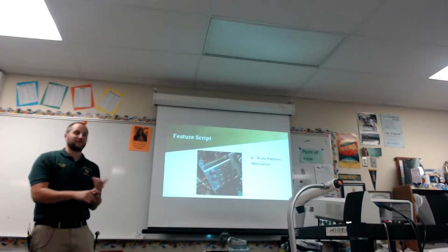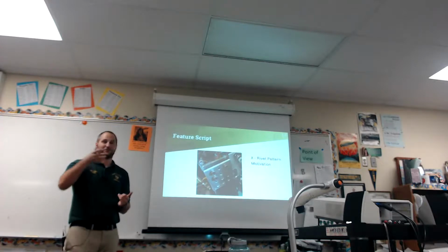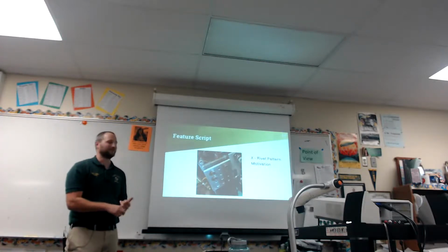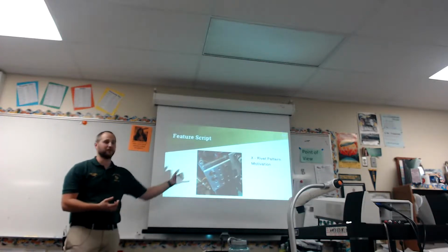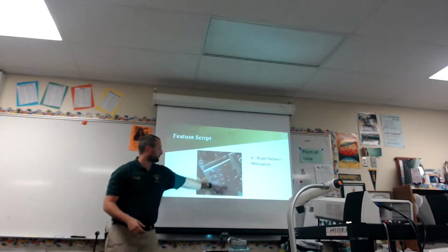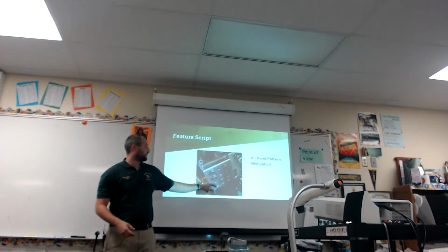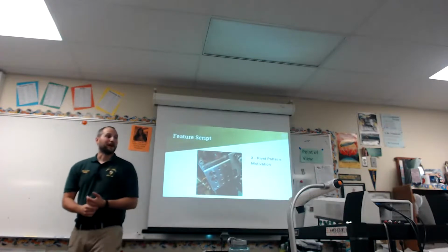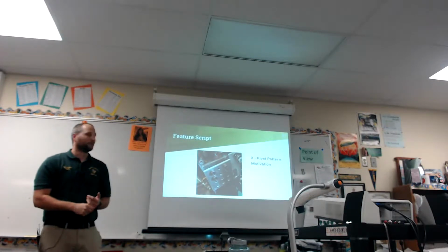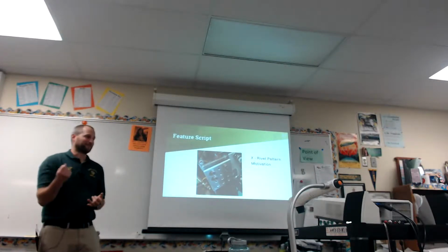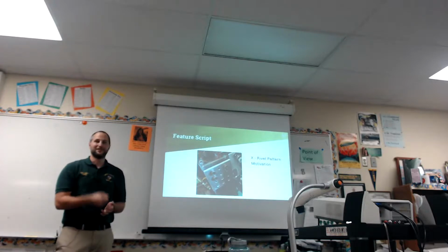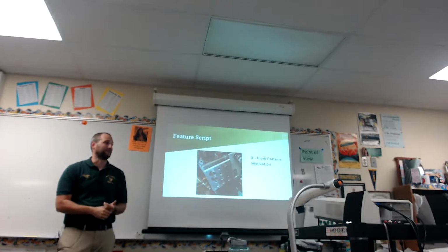And one of 3 things happens. You have some screws that go in there, and your mechanical team's like, why are there all these holes in here? And then your part's weaker, and it breaks. This metal plate was fabricated at an event because the polycarbonate piece underneath of it cracked because of all the rivet holes that we put in it. Or you get a rookie, and the pneumatic rivet gun comes over, chunk, fills all those holes up with rivets, and you have to make a change on something, and you have 27 rivets to drill out. Not fun.